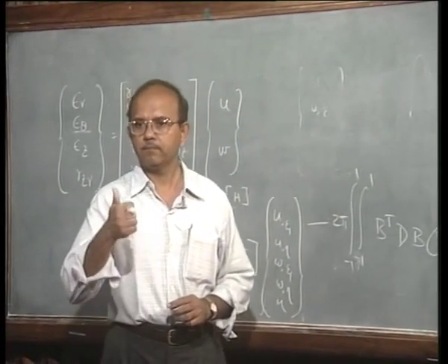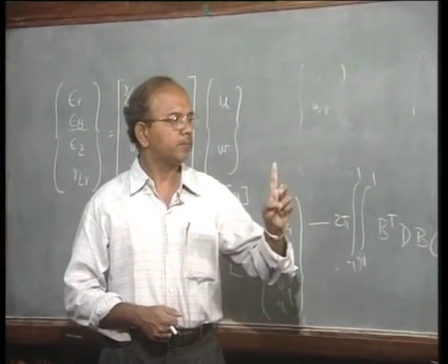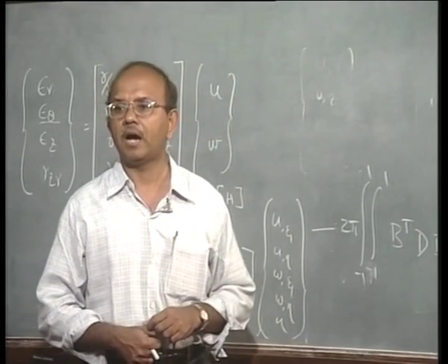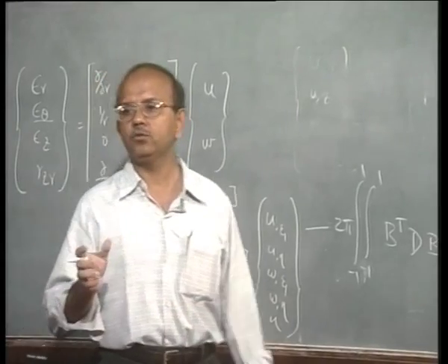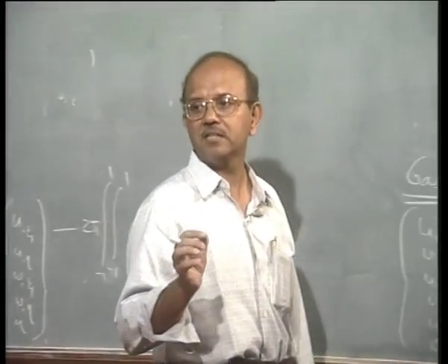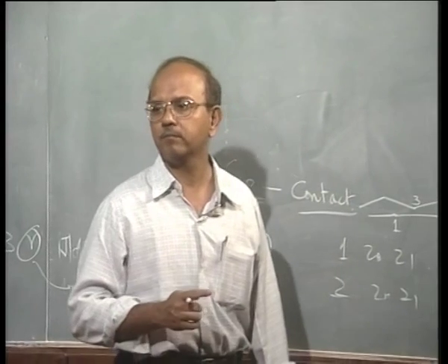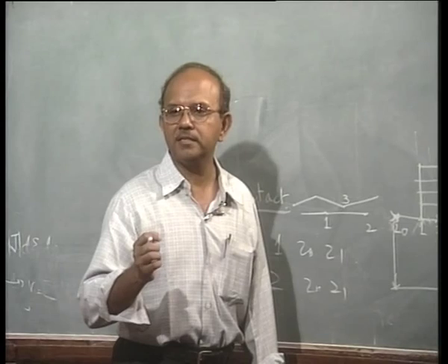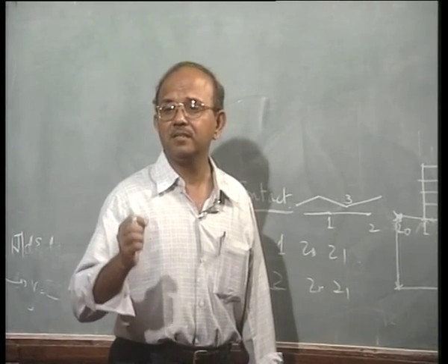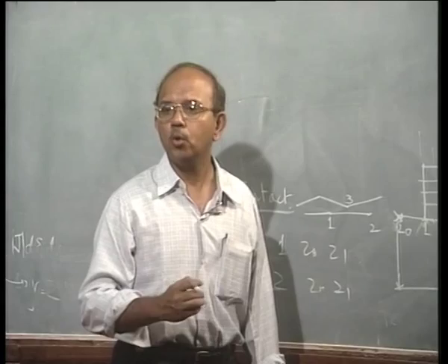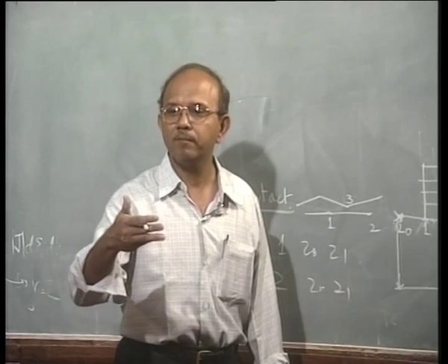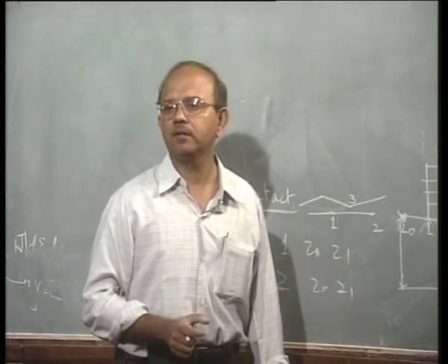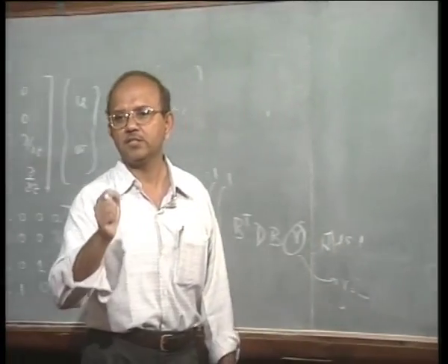Okay, right, fine. Please note that when I define the contact element, I need to make the algorithm recognize which is the segment in which it is operating. It is very important to realize that the algorithm inside a software would search and find out which is the segment of the master element, or the rigid body, that it is operating.